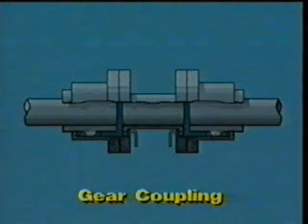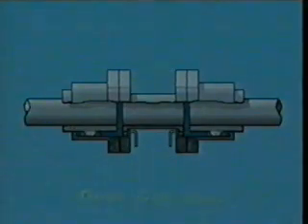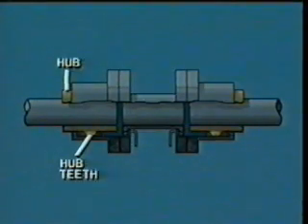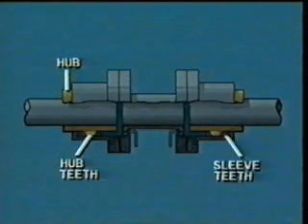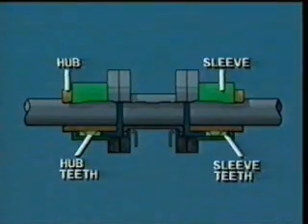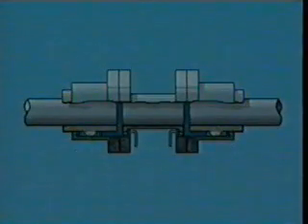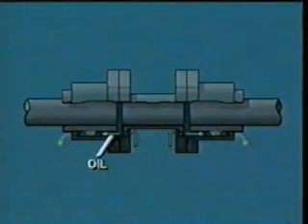Gear couplings are widely used in high-speed, high-load compressors. They work by allowing their parts to slide or otherwise move relative to one another, with no deliberate bending or flexing. External teeth on the hub of the coupling are free to rock back and forth or move axially within the internal teeth of the sleeve. Small couplings are sometimes grease-packed. Large, high-speed couplings use circulated lube oil.